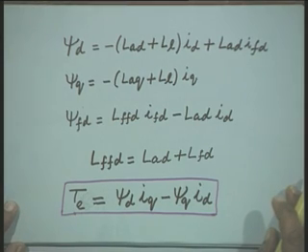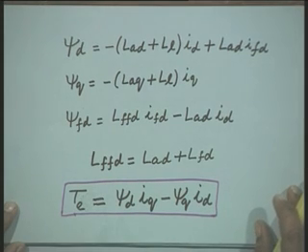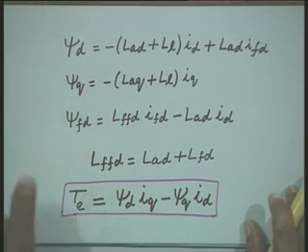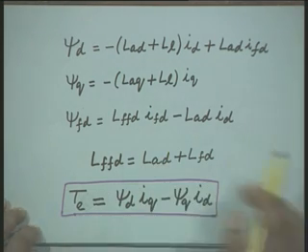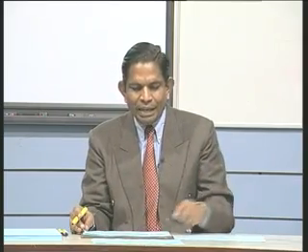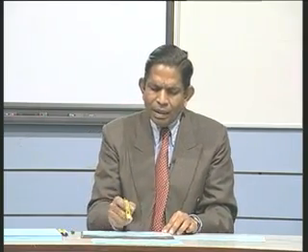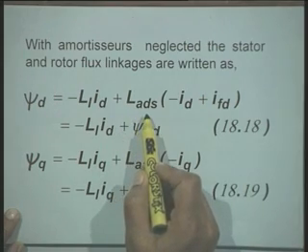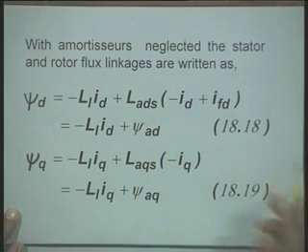Instead of using the unsaturated value, we will be using the saturated value, and the saturated and unsaturated values are related by the saturation coefficient. Therefore, in the equations for psi d and psi q, LAD is replaced by LADS, that is, we are using the saturated value.